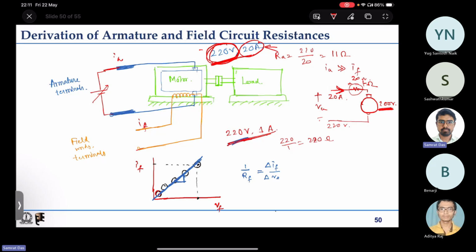Okay, now let us start doing the experiment. When doing this experiment for the armature, the voltage source can be quite low, because the motor is not rotating and we are not exciting the field, so there is no flux and no torque production.